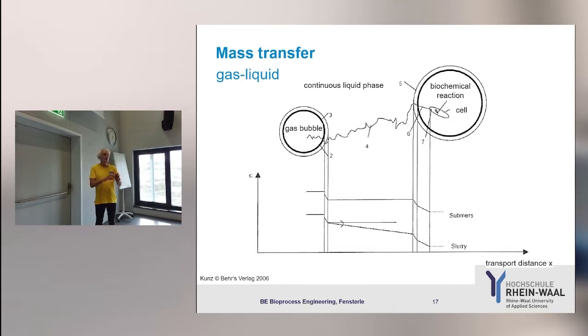However, of course, if it's no more a dispersed single cell, but we have agglomerates of cells, then things are different. Then we need to first get into this agglomerate, especially if they form capsids or whatsoever, so a gel around or so, then it's just diffusion. And the other evil thing is, then it's of course not an even distribution. So the outer cells will have a different concentration than the inner cells, and there will be a different driving force. In this case, of course, we cannot neglect it. So this is the reason why we always put the stirrer at a speed that we don't have that, because again, we hate calculating around in these conditions.